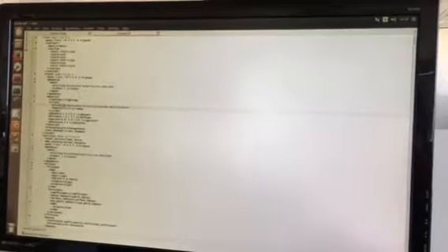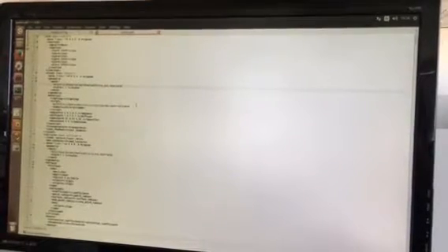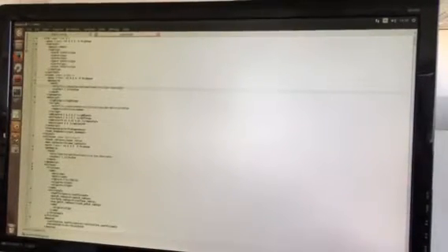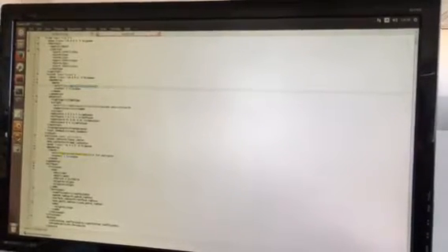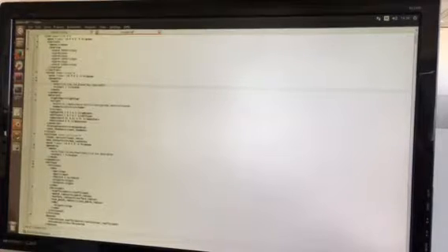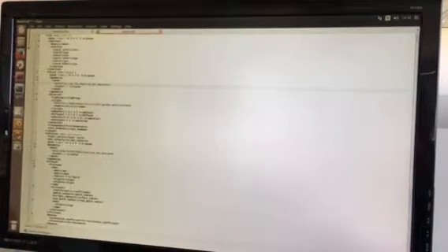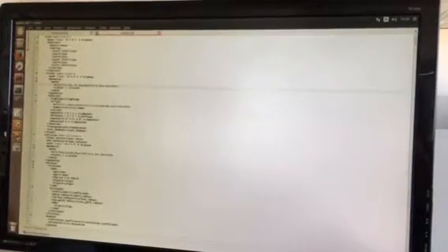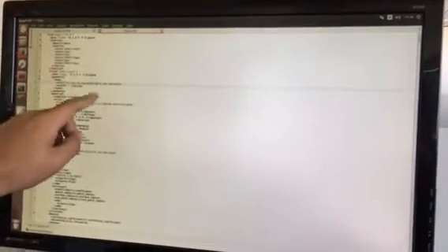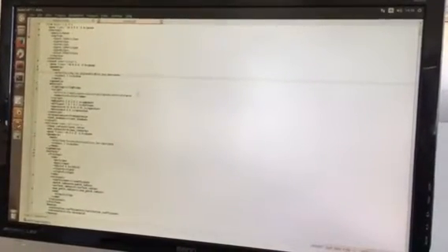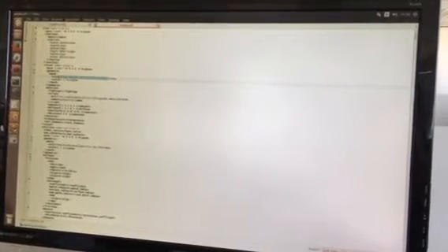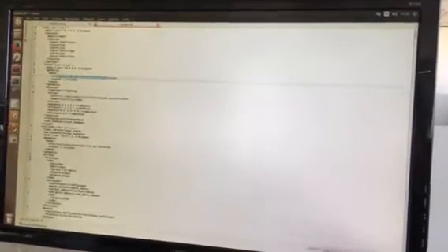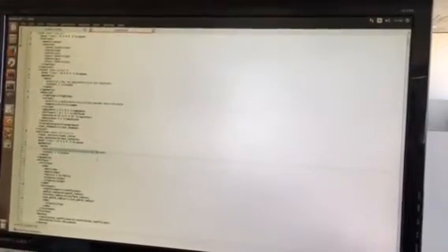It's file, then two slashes, and then here the name of your ROS package, my ROS package, and then probably you'll have your models inside a folder called models or something like that. And then finally the Collada file. Here for the Collada we are using visual and also collision, which is here.